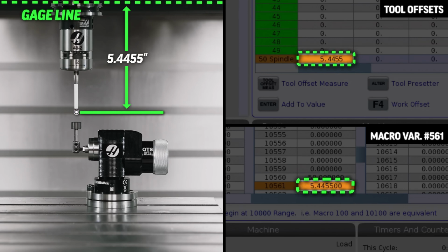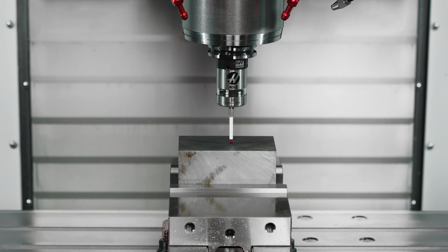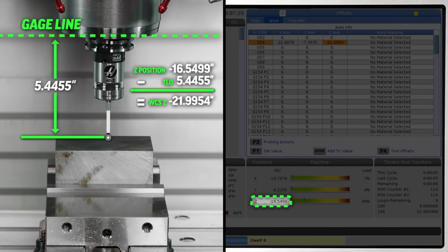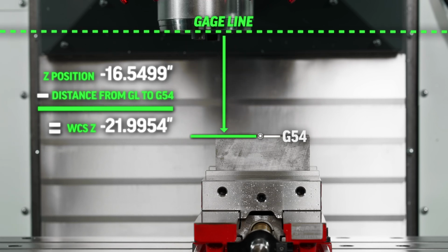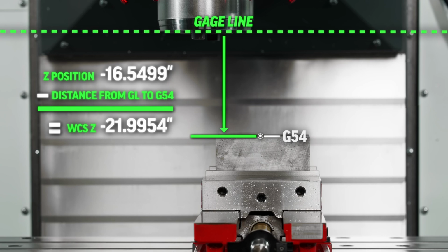When we probe the Z-axis top of our part, the control will take this machine position as the spindle probe is triggered and subtract the tool length offset of our work probe and use this new value as our G54 work offset Z value. Machine Z position minus our probe length offset. Now with that probe length removed from the equation, it means that our work Z0 is really just the machine position where our spindle gauge line meets our part.